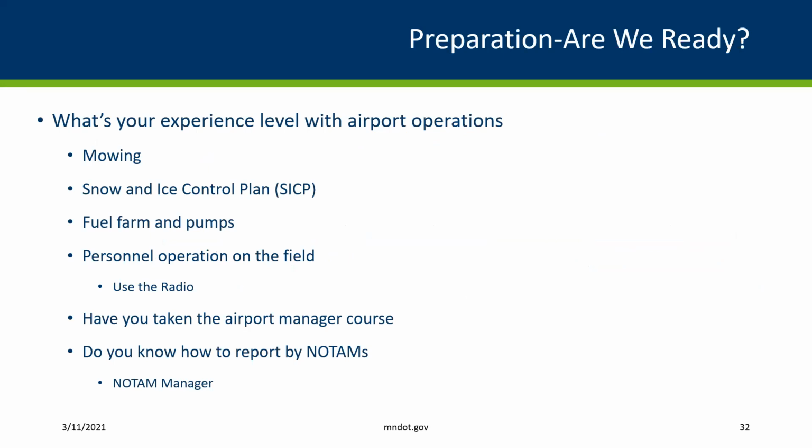Your snow and ice control plan. Where do you put your snowbanks? What are your priorities? If you have multiple runways, which one is your priority runway? Which taxiways do you make sure are plowed first? Where do you put the snow on the ramp?